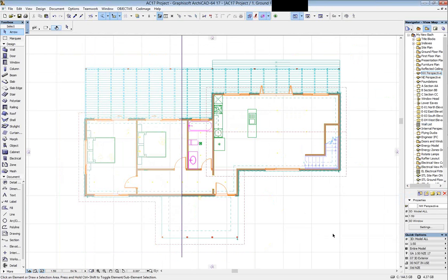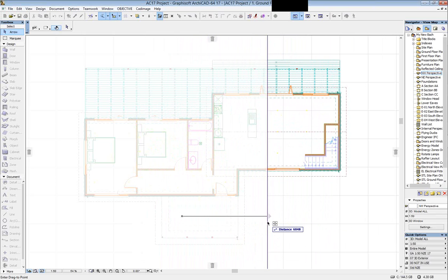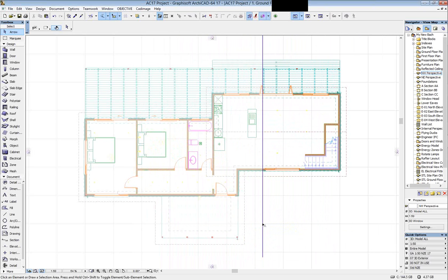I'm going to go back to my floor plan. This is new, however. The cutting plane is now showing on my floor plan. So I can drag that cutting plane along, and where my building is grayed out is where it's cutting, and where it's solid is where it's not. But what we thought was quite cool about this is we could set that cutting plane to align with a section. And then we've always got white space on a section view. Why not put a 3D of the section in that white space? Better still, grab that section 3D, save it as a 3D document, and add some additional text and notation to it.